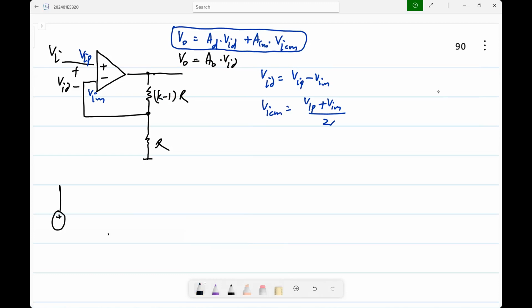One of the common cases is you have, let's say, a battery, and you have some circuit powered from it. One of the common things that you see is to keep track of the state of the battery. Obviously, all of you have phones and it shows you how much battery is remaining. That is done by what is known as Coulomb counting. That is, you measure how much current is flowing, basically how much charge is coming out of the battery.